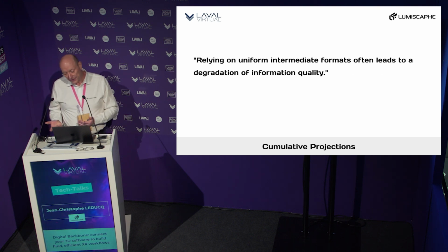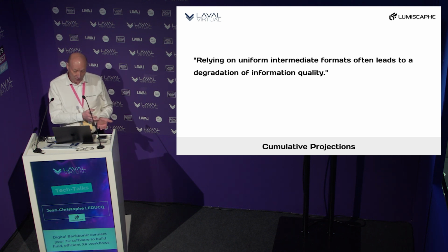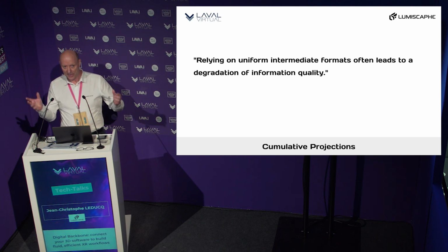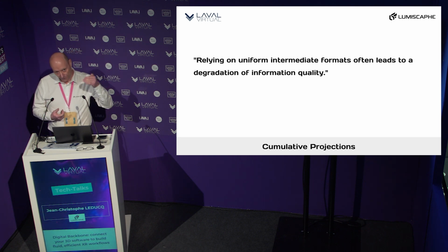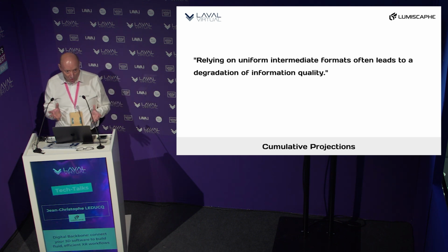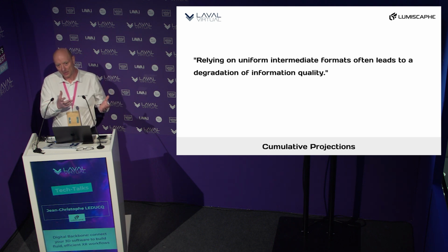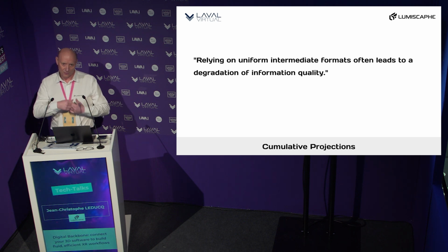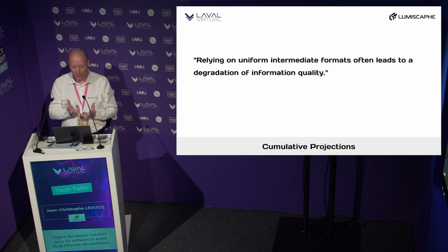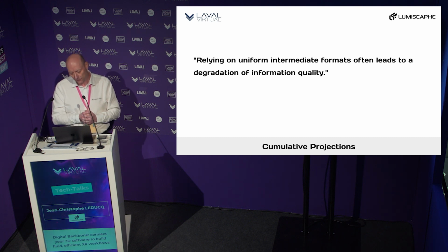Another consequence of that is that we have seen that if you are using an intermediate file format like FBX, for example, or USD, you add a projection step. Look, you may introduce more artifacts in your data. So you must keep in mind that if you choose to store all your information in OpenUSD or FBX, you have a first projection to go into that uniform world. And then perhaps you lose information, and then you go from that standard world to other specific worlds. And once again, perhaps you will lose information. So you have to be careful when you are doing projection. We have to take care of our information when we are doing that.